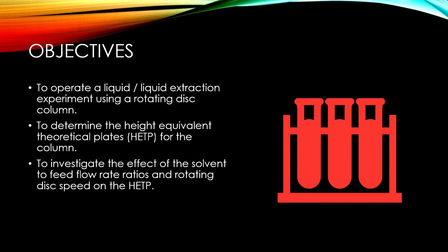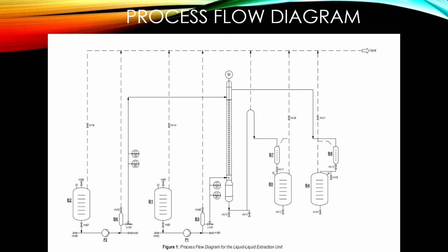Objective: first, to operate a liquid extraction experiment using a rotating disc column. Second, to determine the height equivalent theoretical plate, HETP, for the column. Third, to investigate the effect of the solvent to feed flow rate ratios and rotating disc speed on the HETP. Process flow diagram.